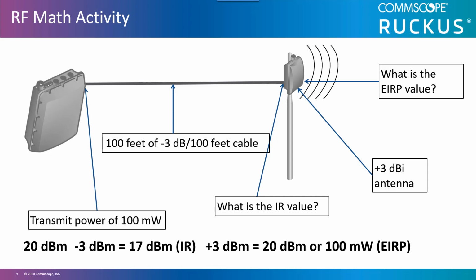Quite often, you may run into antennas that are not 3 or 10 compliant. You may have something that's a 14.5 dBi gain antenna. Then you're going to have to start looking at real calculators for that. And you may not have an exact cable length equal to the loss per the specified distance. You also have cables with connectors and attenuators and lightning arresters and amplifiers and other things connected. So you may need to measure the power at the cable using some specific equipment made for that purpose to know exactly what's reaching the antenna.